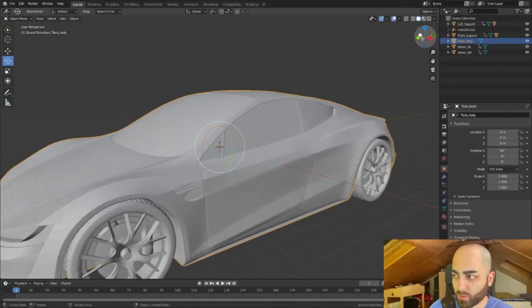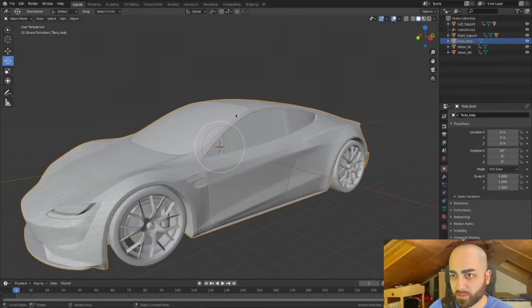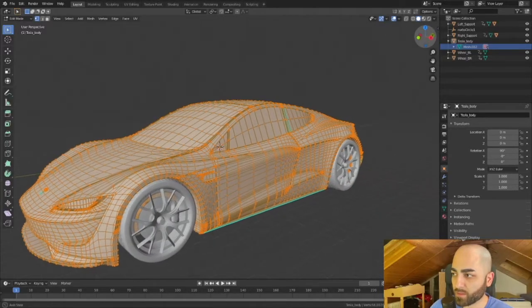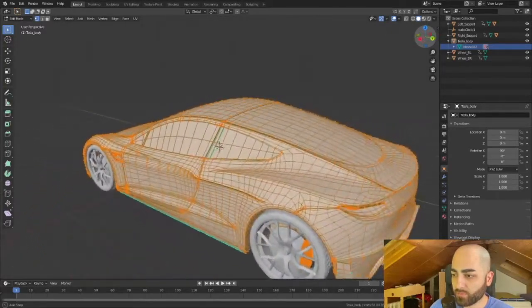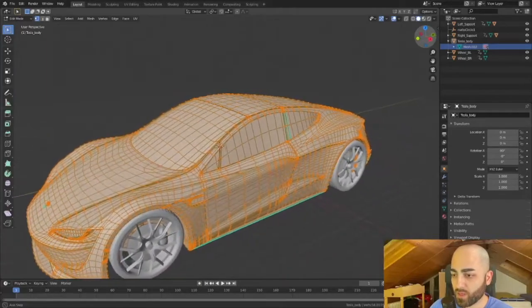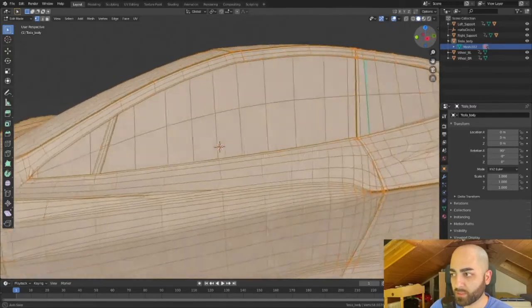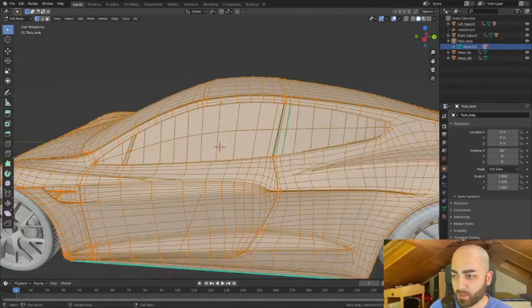I'm not going that deep into Blender, but I can tell you one thing, so that you can work with some meshes here. A mesh is just, let's say, a combination of a lot of vertices merged together and building a 3D object. Okay, now let's say you want to separate this door from the Tesla body.